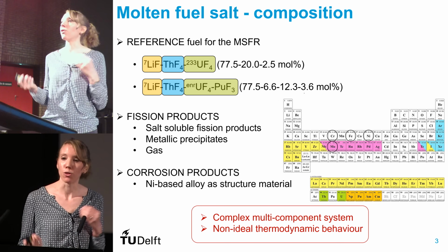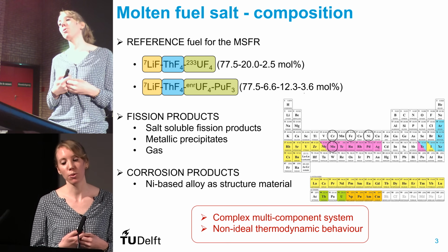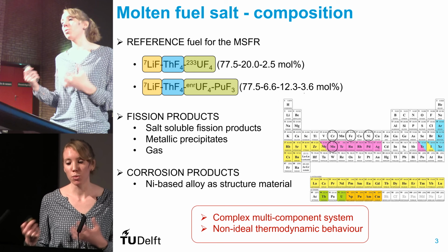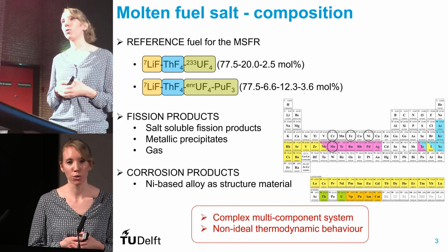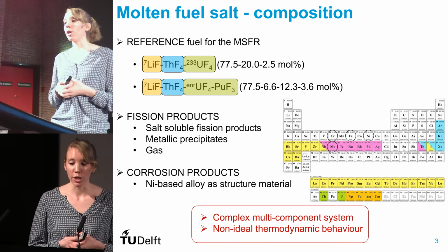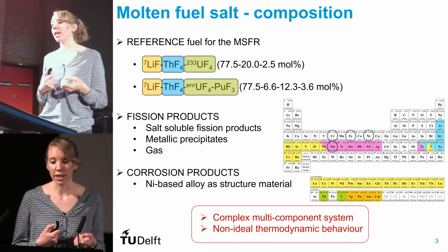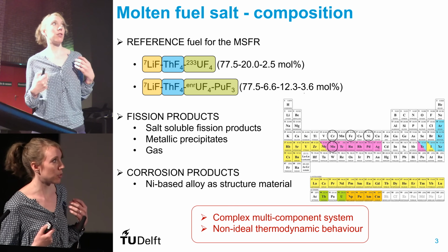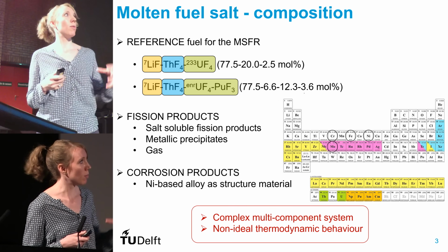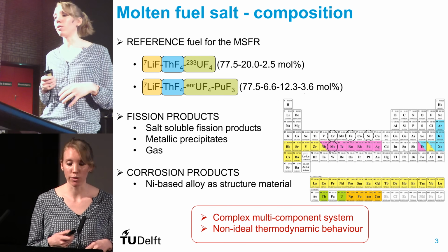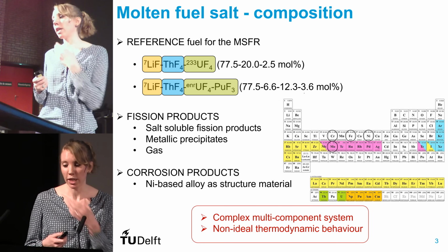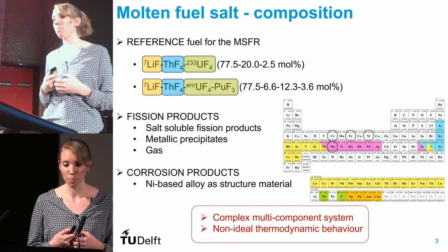And you have not only the fission products, but also some corrosion products that might dissolve in the salt after some time. Because we use a nickel-based alloy, we can expect, especially with fluoride salts, some chromium dissolving in the salt, maybe some iron, molybdenum and nickel.